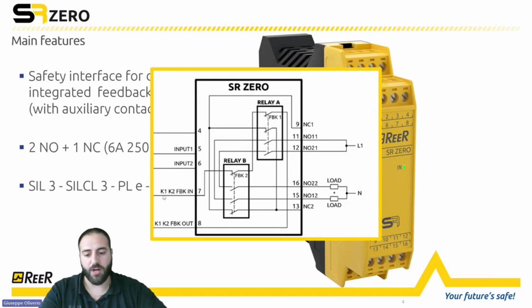As you can see here, you have the K1, K2 feedback inputs, and you can also supply directly from the safety relay, and the series of the two relays are given here as an output to the safety device. In this case, you can connect every safety device with integrated function like EDM or manual reset.